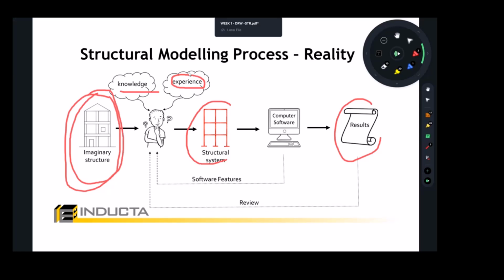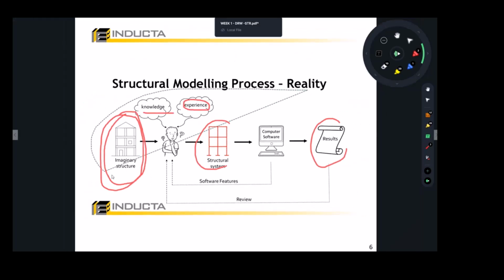You don't need to go and make... usually engineers would go through very well defined calculations if the problem was challenging. The problem is challenging, and you want to use the cores up to their limits, because if they are not working, as I said, you may think about portal frame, if possible. If not, like what I said to you in your assignment, you have to introduce some additional shear walls if the cores are not enough. Okay.